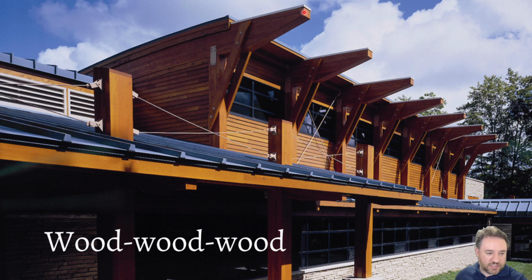As we learned when we talked about moisture in wood, it's much easier for moisture to go into the wood from the end grain, where we have all of the open holes of the straws, than it is for the water to get in on the side grain, which is the side of the fibers, the side of the straws, if we're thinking about wood fibers as straws. So it's important to keep this face dry as much as possible if we want to keep our wood member dry. You'll see we have the same kind of thing over here, where we have a vertical column, and on top it is capped with some steel flashing to keep the top from getting too wet.